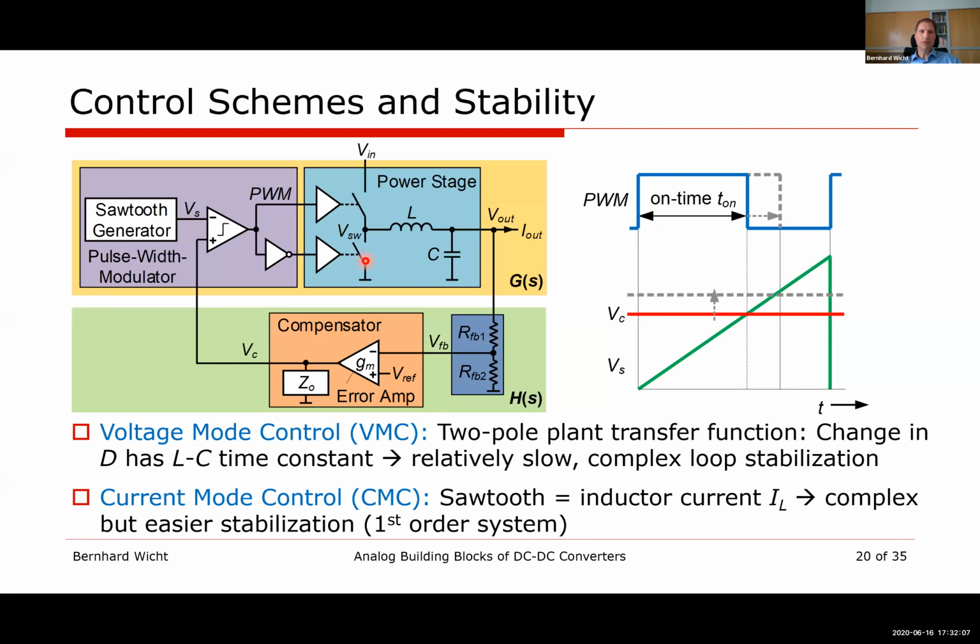That means if we are in a sensitive operating mode, or at maybe low power, we can afford some more switching noise. We would simply decrease the driving strengths of these drivers. We have seen these cascaded drivers. You could change the driving strengths of these inverters. So that would help. Then we have lower EMC or EMI contributions.